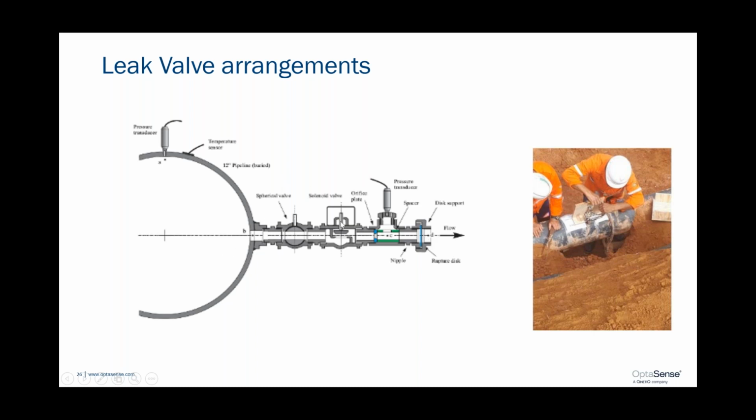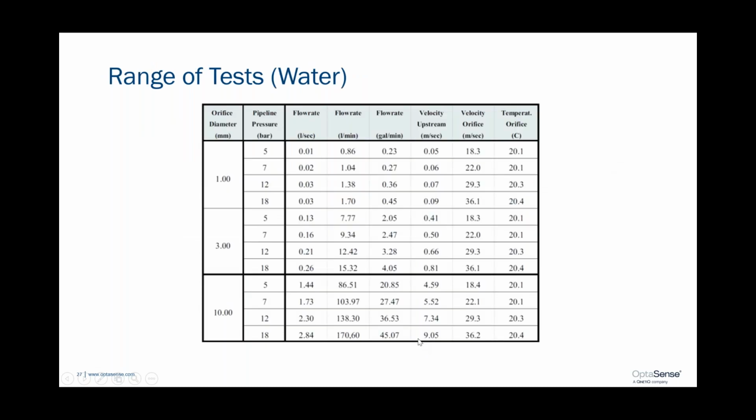We could either open the valve and expose the high pressure fluid to the burst disc and have an immediate failure, or we could reduce the pressure in the flow loop and then slowly ramp it up until we reached the failure point. And the discs were really very effective. They failed bang on the pressure, so we were really very pleased with their performance.